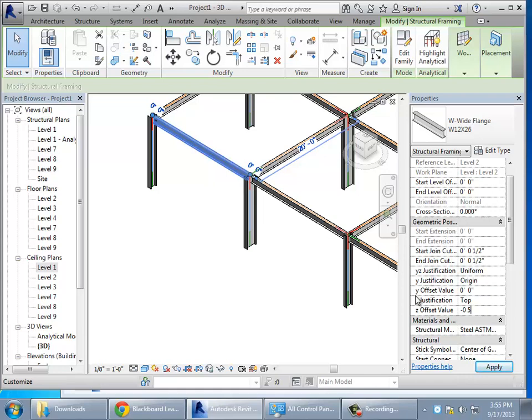You have to explicitly put in the distance. It's not smart enough at this point, at least in terms of what goes on manually. When we get really good, we could write a little extension to Revit that would look at that value for the concrete slabs and automatically adjust the beams. A lot of people are doing development work to create little add-ons that increase the functionality. But the core functionality is you have to do it manually. You want it to be that smart, I know you do, because that would be really, really good.